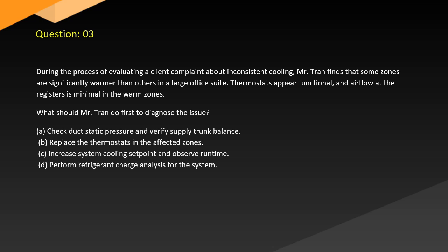A. Check duct static pressure and verify supply trunk balance. B. Replace the thermostats in the affected zones. C. Increase system cooling set point and observe runtime. D. Perform refrigerant charge analysis for the system.